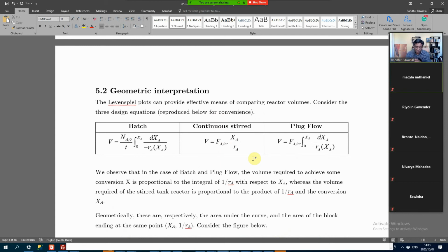And that's because the CSTR is perfectly mixed everywhere. So in all space, it's the same. And also when we say CSTR, normally we mean steady state. So it's the same both in time and space. That means if you have a high reaction rate or a high conversion, then you have the same low concentration everywhere in that CSTR. So we said all this, right?